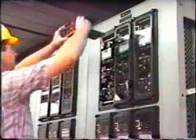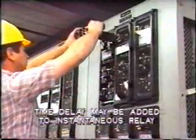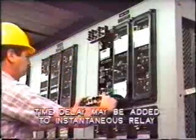At high voltage, say 345 kV, it takes about 21 cycles for the air gap at the fault to deionize. If we reclose the breaker too soon, the fault arc would immediately restrike. To prevent this occurrence, a time delay between opening and closing is usually built into the breaker by the manufacturer. The actual time will depend upon the nominal breaker voltage. In addition to this, a minimum time delay, say 5 cycles, may be added to the instantaneous relay operation. So the total time delay for reclosure may be about 35 cycles.